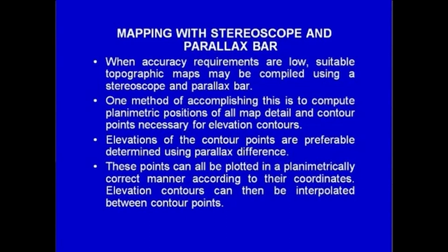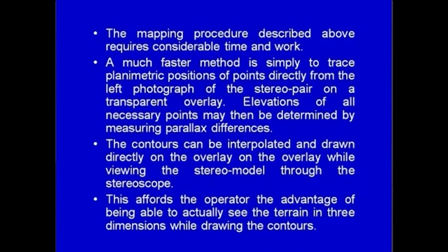Elevations of the contour points are preferably determined using the parallax difference equation. These points can all be plotted in a planimetrically correct manner according to their coordinates. Elevation contours can then be interpolated between the contour points. The mapping procedure described above requires considerable time and work.